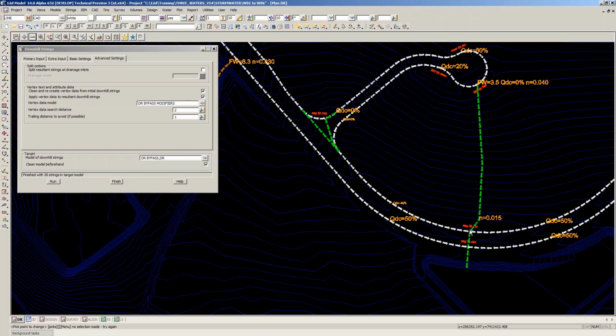None of that, by the way, affects how much flow actually gets to and into the pit. That's already been predetermined. After we've figured out what the rational method has told us, we want to figure out how the water gets to the node. And this is a preliminary calculation, if you like, before you actually worry about what gets into the node. But nothing about what you do with these percentages affects how much flow gets into the node and into the pipe system. It's purely talking about how the catchment flow assigned to each node comes down each of the approach paths towards it. And again, it's only the nodes that have more than one approach path that you need to do anything.